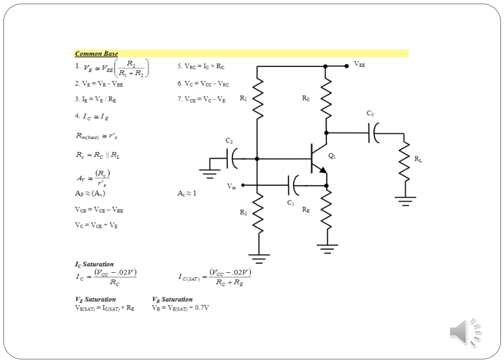Let's look at the AC characteristics, right? So the input resistance here, R sub in of the base, is approximately that R prime E. So remember, something very, very low. Output resistance is RC in parallel with RL. The voltage gain, AV, is equal to R sub C divided by R prime E, so it's a strong gain. Current gain is equal to 1. Power gain is equal to the voltage gain.